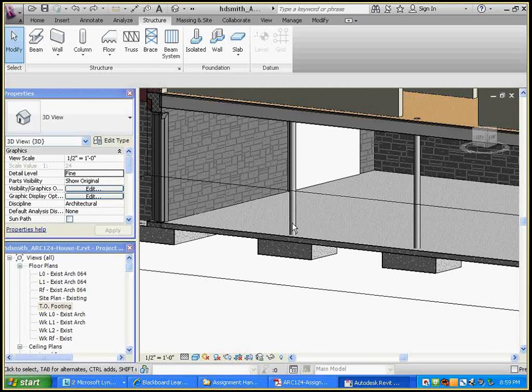Well, you don't really attach the bottom of something to the... you can attach the top of the column to the underside of a beam or a floor, but you can't attach the base of the column to the bottom floor. Are you talking about the top of the column? Yeah, top. Actually, we're going to put a beam in there, and then we'll attach the top of the columns to the underside of the beam. And so then where the beam is depends on one of two ways that we could frame this basement. So that's our next challenge, and that's the step D here.